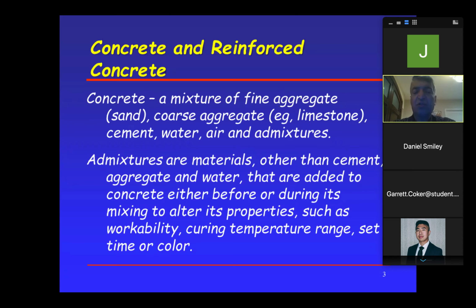Okay? So again, the way you mix concrete, it depends. You have to be very careful, and the proportions are going to affect the strength. Of course, a very important one, I can tell you, is water. The more water you use, the weaker the concrete is going to be. We'll talk a lot more about that, but this is the first warning I give you: be careful of adding too much water to the mix.